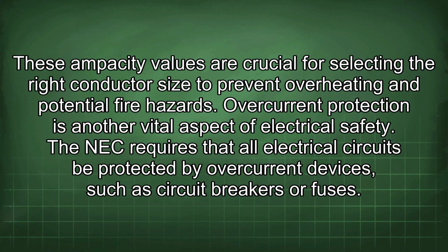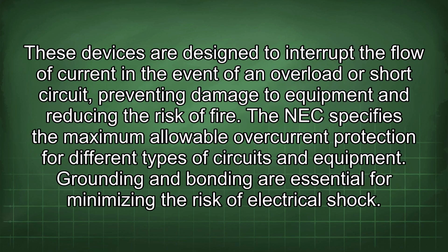Overcurrent protection is another vital aspect of electrical safety. The NEC requires that all electrical circuits be protected by overcurrent devices, such as circuit breakers or fuses. These devices are designed to interrupt the flow of current in the event of an overload or short circuit, preventing damage to equipment and reducing the risk of fire. The NEC specifies the maximum allowable overcurrent protection for different types of circuits and equipment.